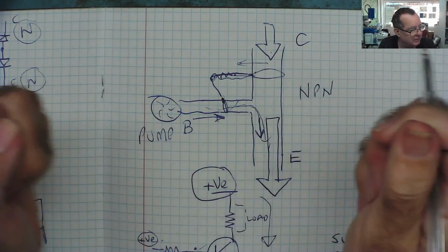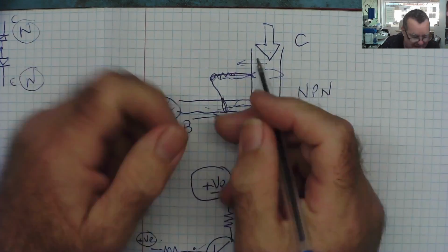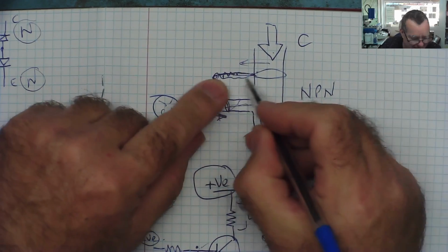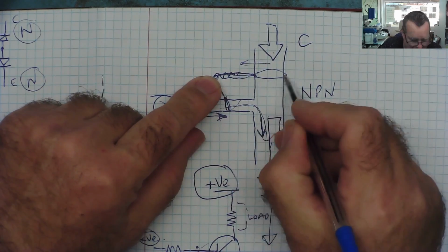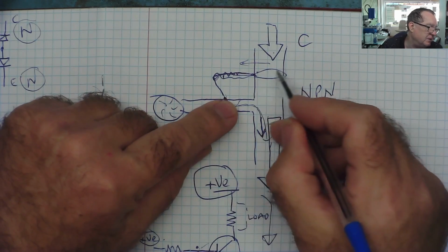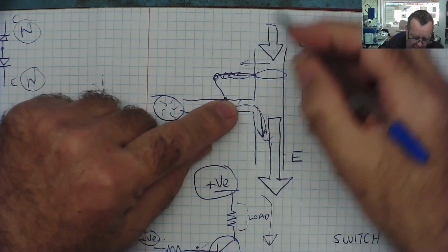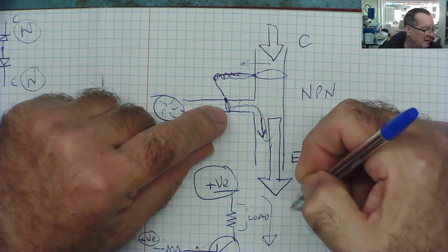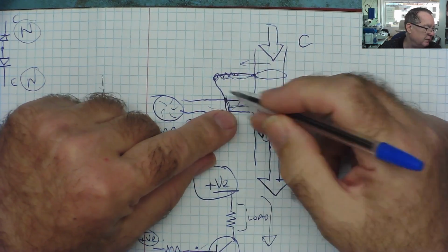It will stretch. As well as moving this, it can stretch. So at the right pressure, it starts to turn on, but because this can stretch, like elastic, this doesn't move as much as it should. And even when this is fully open, it is not open enough. So effectively, the current flowing through here is less than it should be when this is fully conducting.